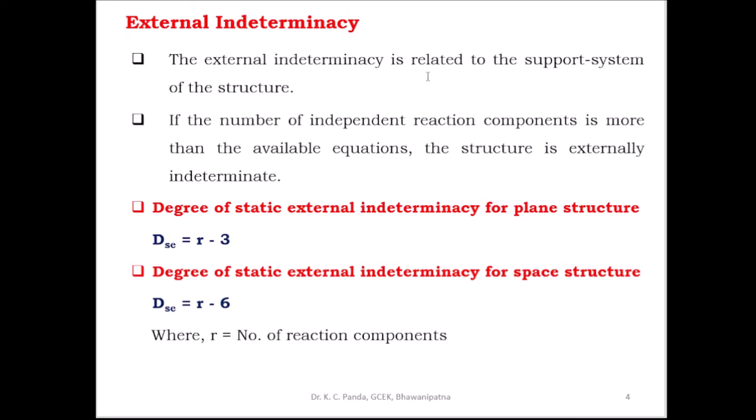Then coming to the external indeterminacy. The external indeterminacy is related to the support system of the structure. If the number of independent reaction components is more than the available equations, the structure is externally indeterminate.